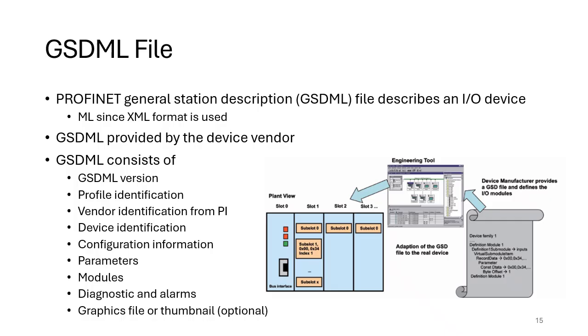Now you can look inside the GSDML file. It is human readable, but not really, because first of all they can be very, very large. A GSDML file of up to 5 megabytes is not impossible. The GSDML file does include a picture of the device as well, which is used for snapshots and in the engineering tool. So sometimes a large part of that GSDML file can be the picture.